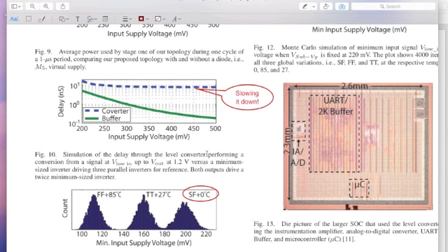So when will the level converter break? It's when the NMOSes are not able to overcome the PMOS. So what process condition, what temperature condition will lead to that problem? NMOS has to be made weaker. That means you have to use a slow NMOS process condition. That means the NMOS thresholds are higher than what you expect them to be.